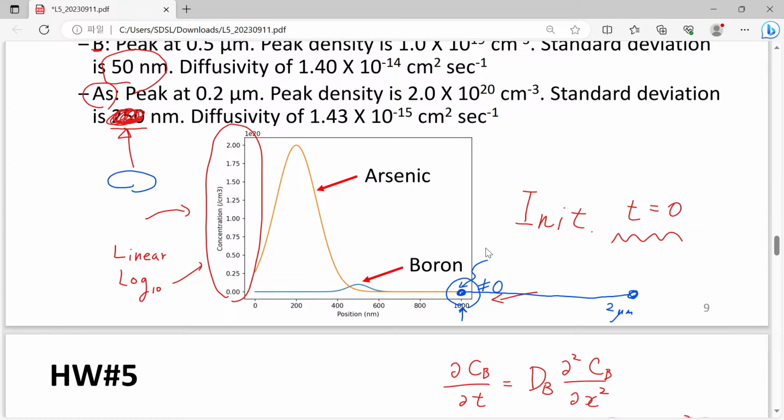So always the condition is, the boundary condition should be reasonable. And if we introduce this shorter boundary, then we will introduce some distortion into our solution. The best way would be an extremely long simulation domain, but that will increase our computational effort.